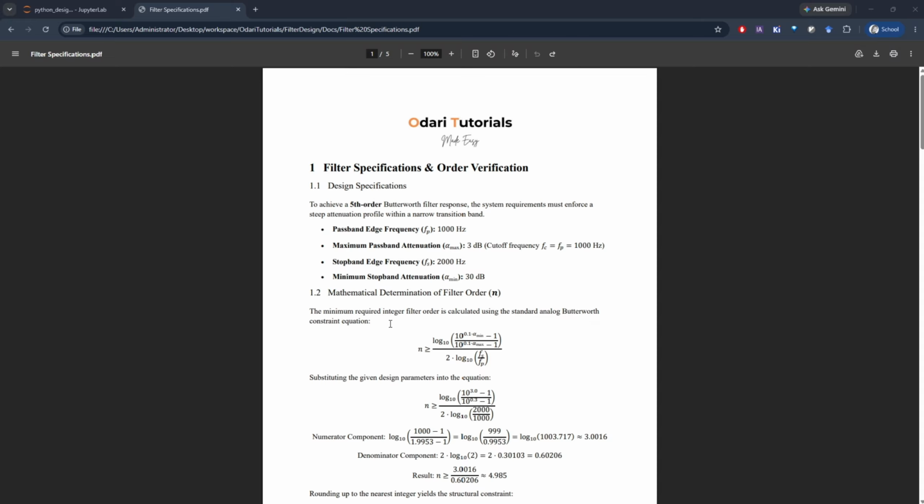transfer function, right? And be able to maybe now do the scaling, because for the first time we use normalization, because if you use normalization, you can be able to scale to any value that you want. Maybe having a normalized transfer function makes the simulations very easy. Maybe you want to design any kind of filter of the fifth order of any kind. Maybe you have different values, you can be able to scale them and get the values from that filter order.